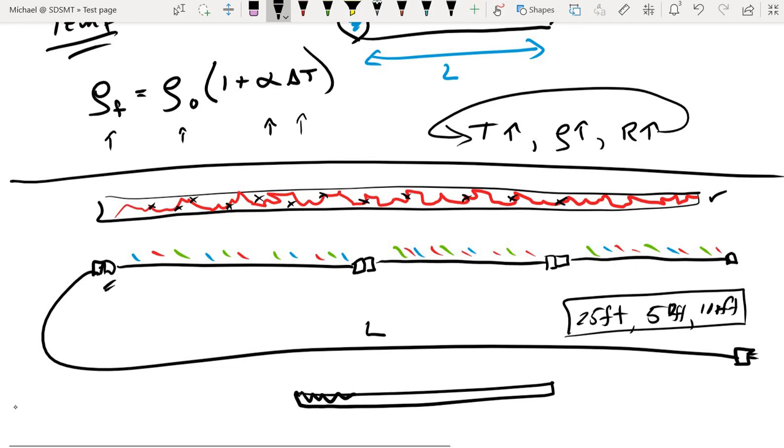And the reason those cords are so thick is so that we can increase the cross-sectional area, thereby decreasing the resistance of the extension cord. And whenever you make any kind of cord thicker, that's more material that's required, and so that's going to drive the price up.